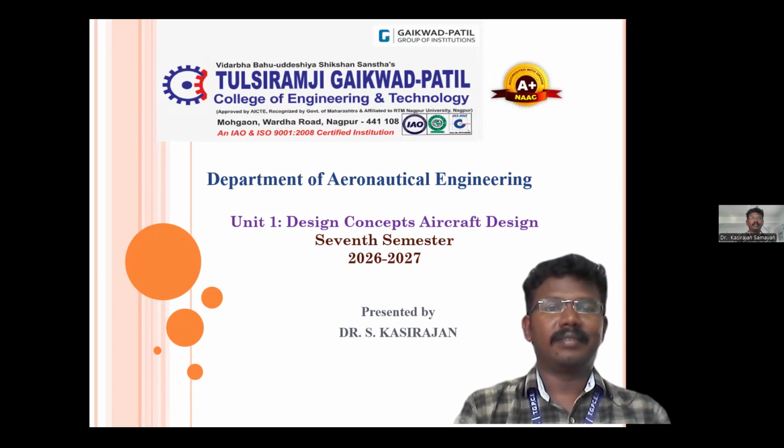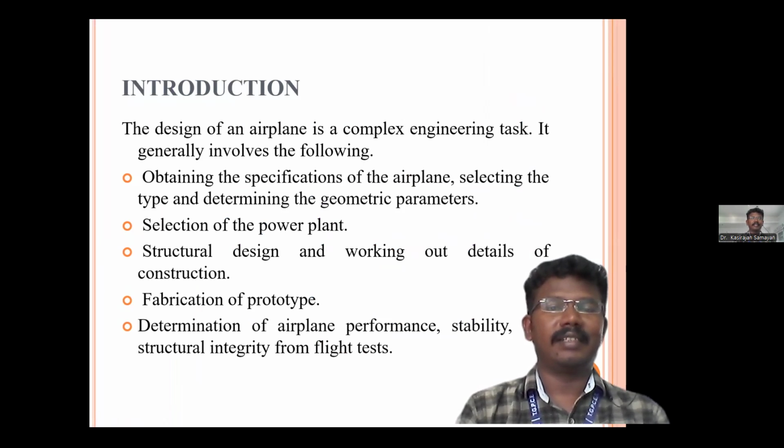In aircraft design, the first unit topic is design concepts. The introduction of aircraft design: it is a very complex engineering task to create your own design or an innovative design. We need to consider the specification of the airplane, selecting the type, determining the geometric parameters, selecting the type of power plants, structural design, and working out details of the entire construction. And we have to prepare the fabrication of the prototype. Finally, we need to check or analyze the airplane performance, stability, and structural integrity from the flight test.